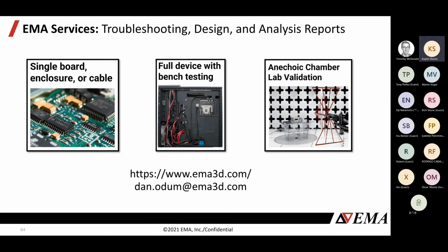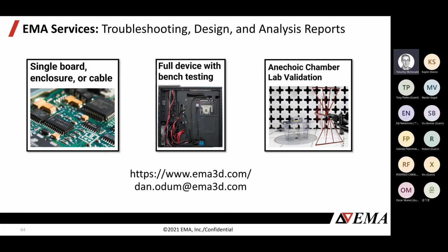All right, next question. What information do you need from us for EMC troubleshooting? Makes sense. If it is number 2, the medium or the large style, we may ask for a unit itself. If we're doing simulation and not doing benchtop or anechoic chamber measurement, we would need things like the board files for the PCBs.